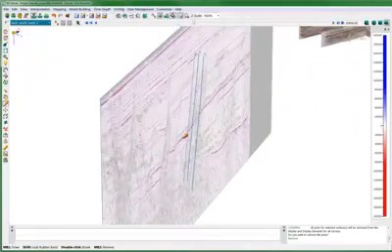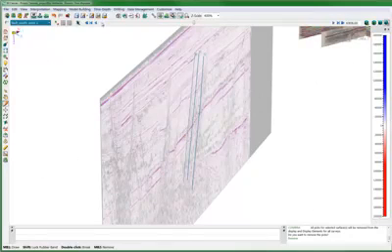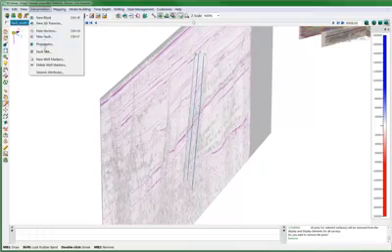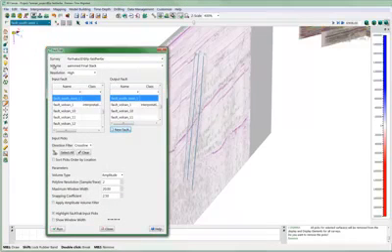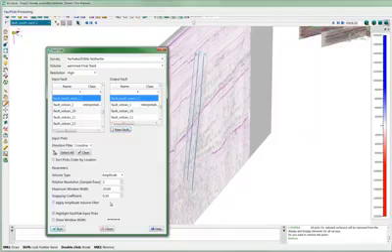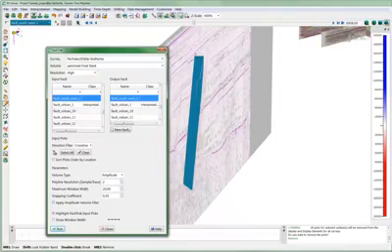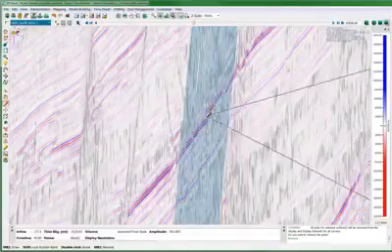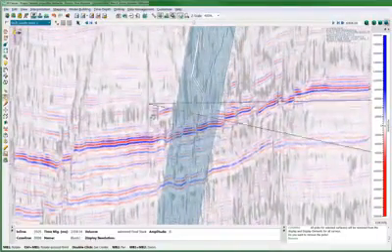We can now use our semi-automatic fault tracker to densify the fault picking. Based on our sparse manual picking, Fault Track is going to compute discontinuity based on the amplitude volume, by specifying several parameters, such as the snapping coefficient or the window width. We are going to tell the algorithm to fit more to our fault picking or to the discontinuity. By clicking Run, we are generating one fault stick per line. Fault Track has generated one fault stick per line.